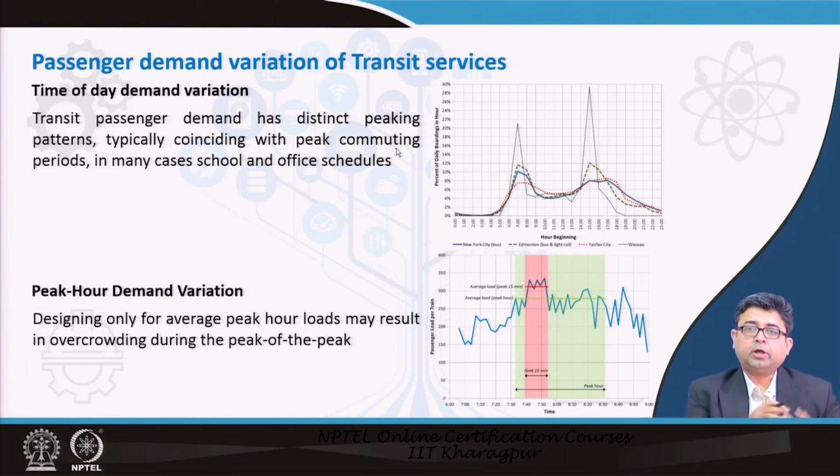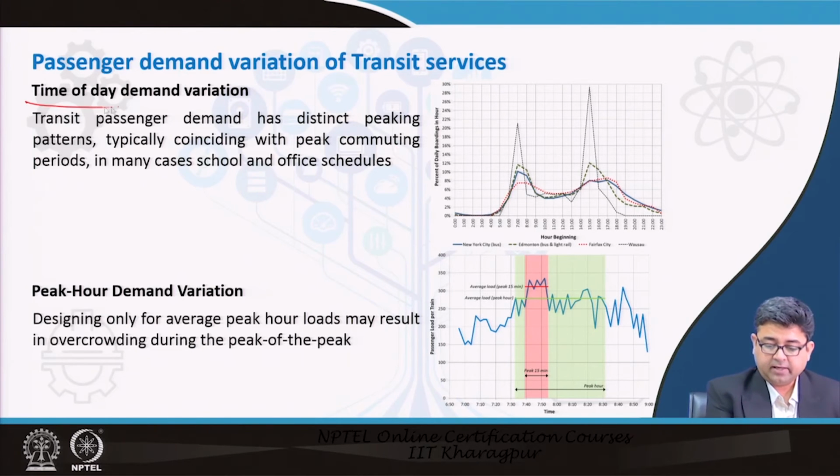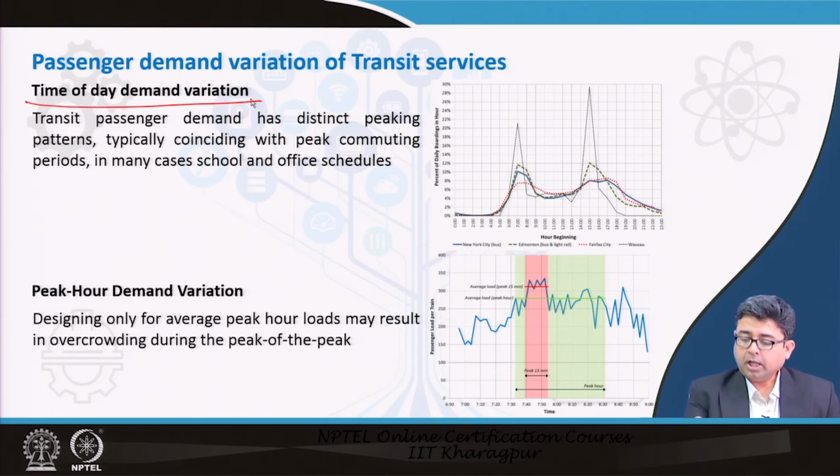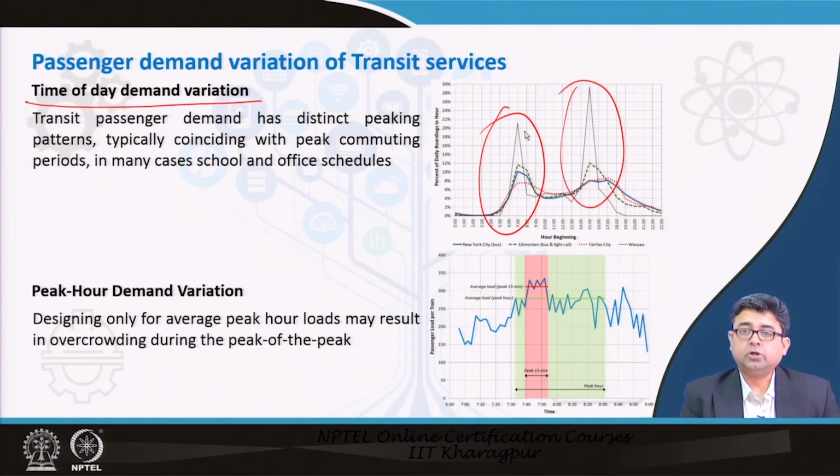Then after knowing all these operational characteristics such as passenger capacity, vehicle capacity, transit speed, reliability, you have to know the characteristics of operations of public transit systems, right. There is time of the day demand variation. Always during the peak hours the demands are higher. So, you run public transport at a much lesser headway during those times, whereas during off peak times you keep the headways longer. So, that also allows your operational cost to be stabilized, to be maintained, right.